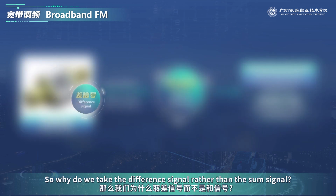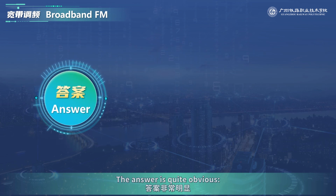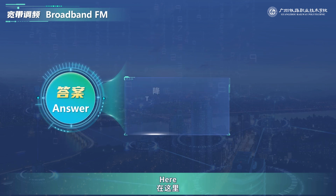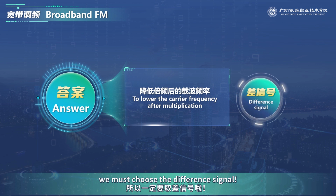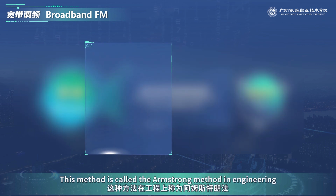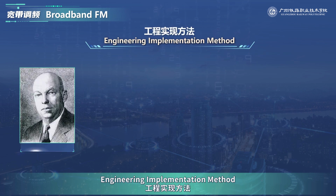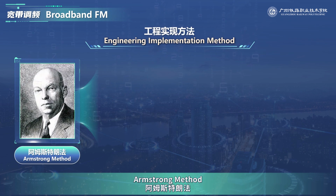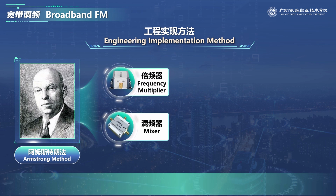So why do we take the difference signal rather than the sum signal? Think about it. The answer is quite obvious. Here, since we aim to lower the carrier frequency after multiplication, we must choose the difference signal. This method is called the Armstrong method in engineering. Engineering implementation: the Armstrong method combines frequency multipliers and mixers.